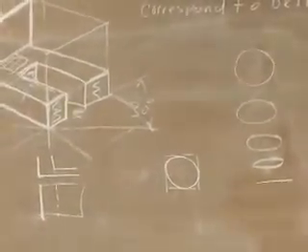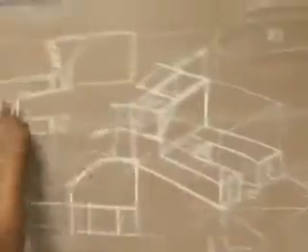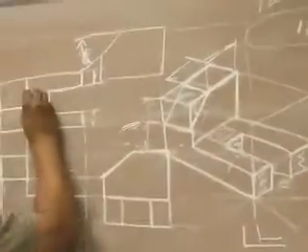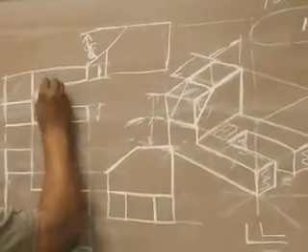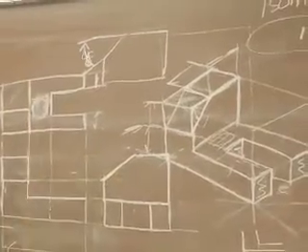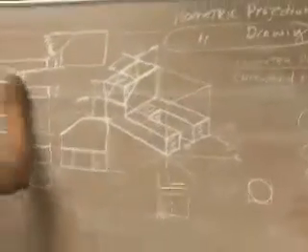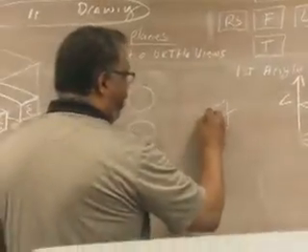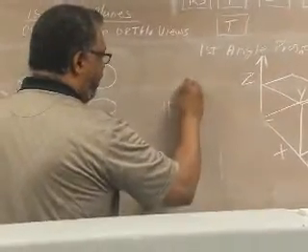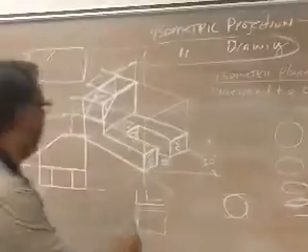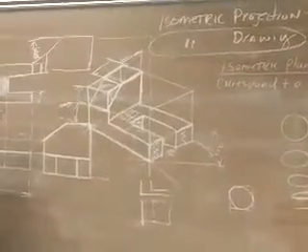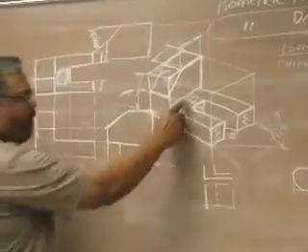and then create a circle based on the size of that square. So if I didn't know this, but I had my grid here, then I know that I have 2 grid squares here, and that would just give me the diameter of my circle here. Now, same thing holds true here. If I knew what it is here, then I could transfer it here. So what I would do is, whatever this square is here, I would draw a square around this axis, because it has an axis to locate the hole. So I transfer,